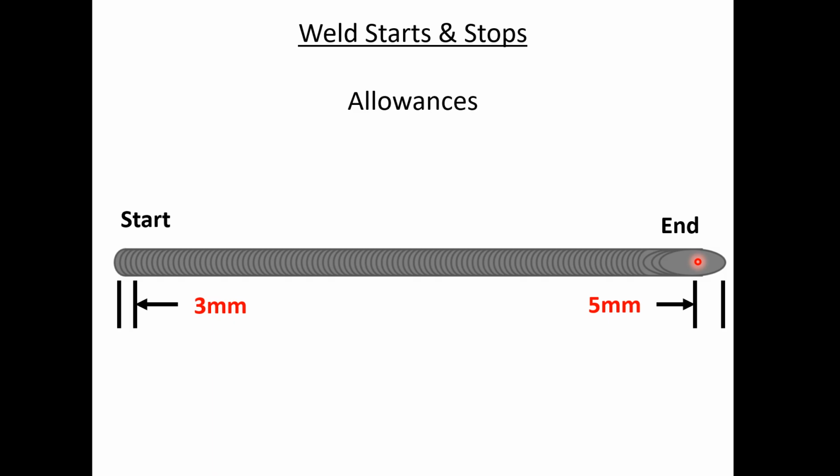And just a quick reflection back into making sure I want the beginning and the end of my weld to be excellent. Right? Most people that would learn welding learn to pause slightly at the end of a weld to make sure that the crater itself is filled. And it was like a broken record. Fill your crater, right? Well, the robots do this as well. They have things on them called crater fills, but under the conditions, sometimes it's very difficult to get a crater fill done. That is a whole new special course on all these setup parameters and how to, like the process of developing all these things and getting them all to work together, how a weld starts, right down to extinguishing the arc and post-finishing the gas.